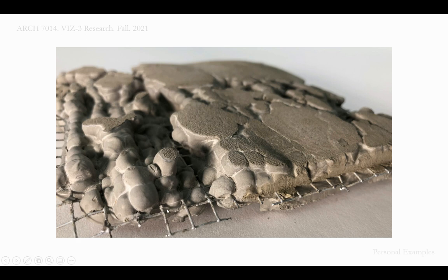But where I didn't let the Z get so close, it creates these super huge valleys. And again, I know where these valleys are going to happen, but because of the randomness of the material, the G-code's always going to remain the same, but things like this ridge will happen again, but it's not going to be exactly the same.